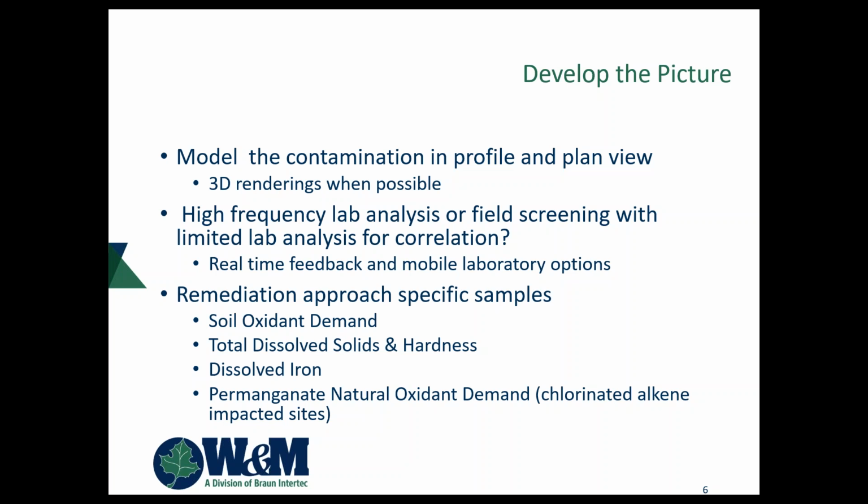Same thing for dissolved iron or hardness. If it might swing towards a pump and treat system or a DPE system, and there's a whole lot of dissolved iron or really high hardness levels in the water, you're going to want to know that up front, because that's additional cost for operations and maintenance, and maybe some additional capital cost. If you didn't know that, you put the system in, and now you've got all this inorganic fouling messing everything up, and a retrofit, and you weren't planning on the cost for the chemical and the other stuff. So just a few upfront considerations.